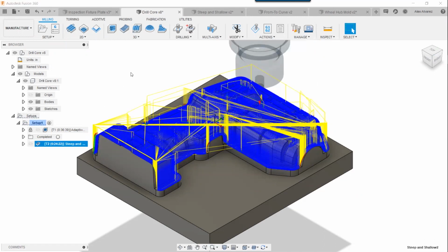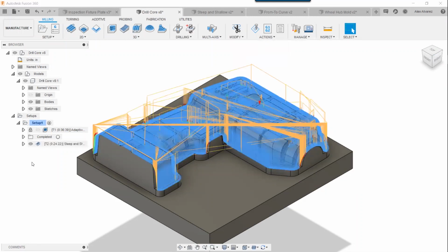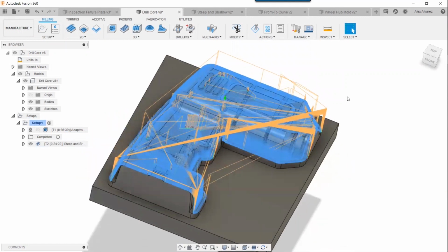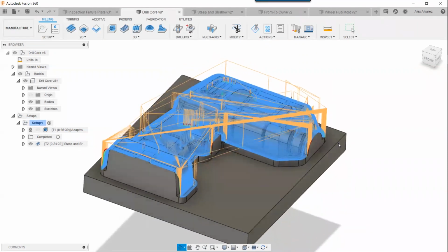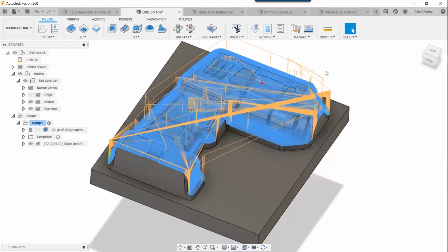So again, there's a lot going on with this, and some added functionality. Maybe you guys are aware, maybe you guys aren't aware. If you turn on the little eye icon right next to it, it's going to lock that toolpath in place, and you can see exactly what that looks like, right? So instead of having to click on the toolpath and just having it visible until you click away, click on the eye icon and it's actually going to lock it in place. Here's another quick tip: if you don't want to see the leads and the links, go ahead and change them down here.